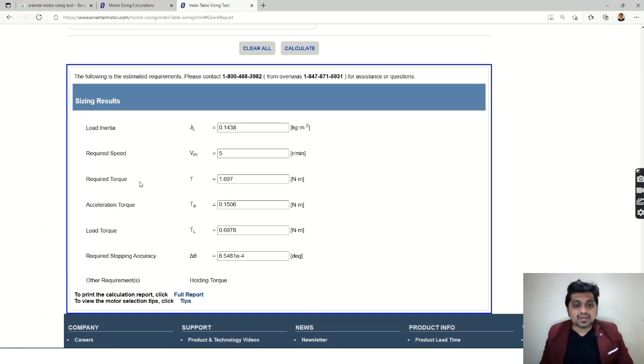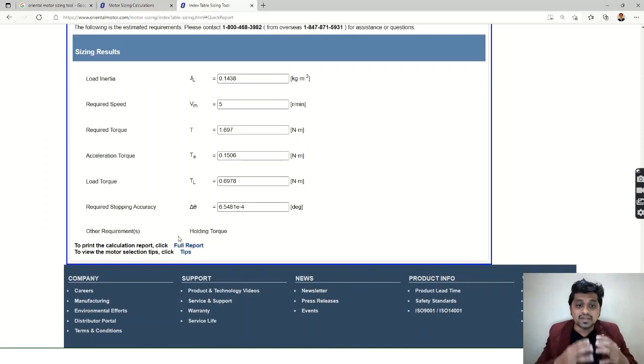The required torque is mentioned over here, because while selecting a motor we will see these parameters in its catalog, but we directly cannot go for that, because here you could see the speed is very less, our motor RPM is very high, so we have to go for a gearbox in between. So it will change some of the parameters. We will see that in the next session, how the gearbox affects these things, right?